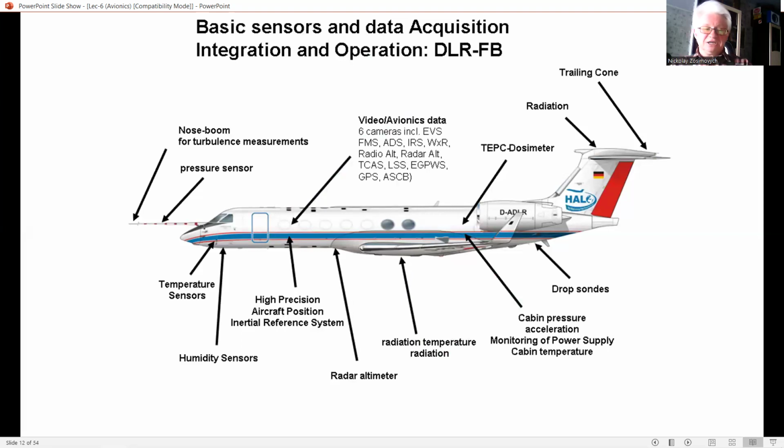Normal acceleration terms from the normal accelerometers are also blended with the other control terms, and the gearings of the terms adjusted at high normal acceleration demands so as to give normal acceleration limiting.